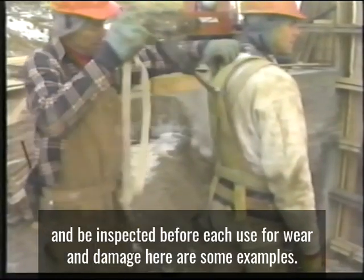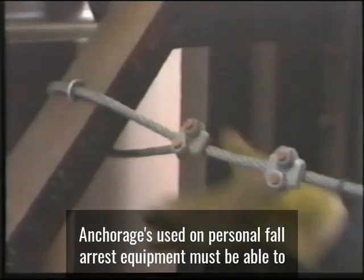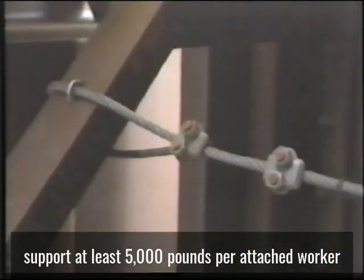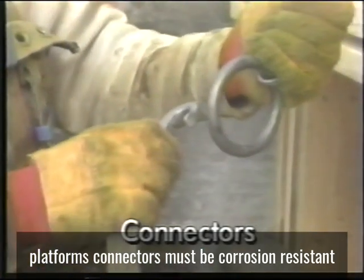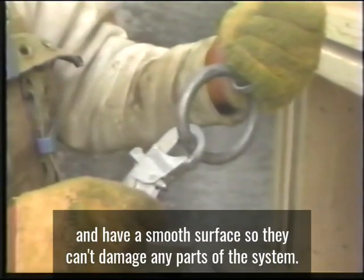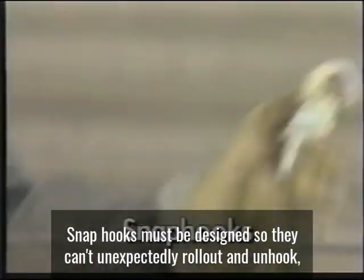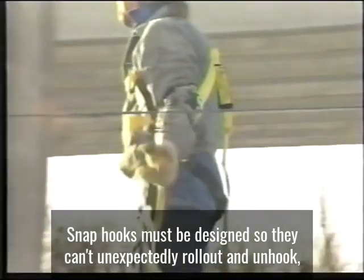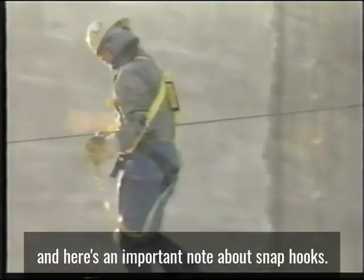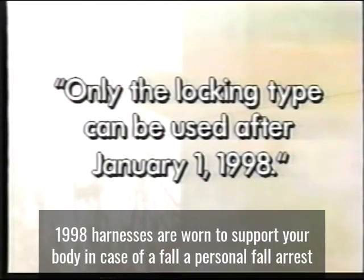Here are some examples. Anchorages used on personal fall arrest equipment must be able to support at least 5,000 pounds per attached worker, and they must be independent of anchors used to support platforms. Connectors must be corrosion resistant and have a smooth surface so they can't damage any parts of the system. Snap hooks must be designed so they can't unexpectedly roll out and unhook. And here's an important note about snap hooks. Only the locking type can be used after January 1st, 1998.